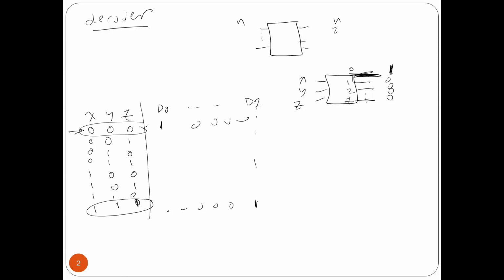For example, if I want to design the AND gate for the first one here, we have one AND gate this way, and then the output has to be D0. And the input here has to be X prime, Y prime, Z prime, because all of them are zeros. So in this specific case, when 0, 0, 0 comes, this AND gets 1, 1, 1, and then I'm going to get 1 here. All the other ANDs should give 0. Okay? Because this one is designed for this min term. So this is this min term. For every min term, we're going to have one AND.